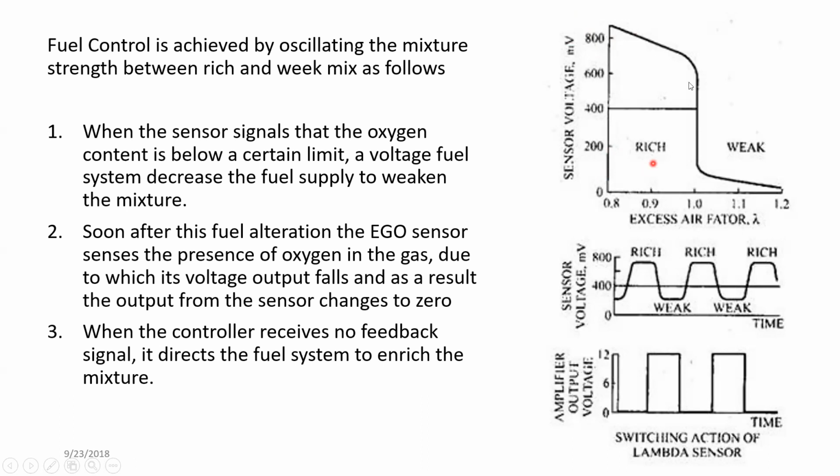So the system tries to maintain around 400 to 450 millivolts, and always tries to maintain the air fuel ratio around 1, that means lambda around 1.